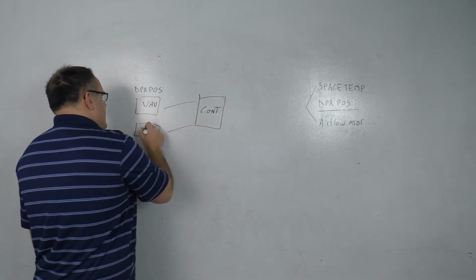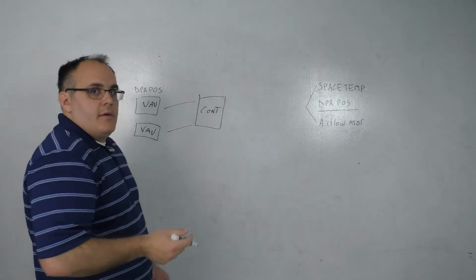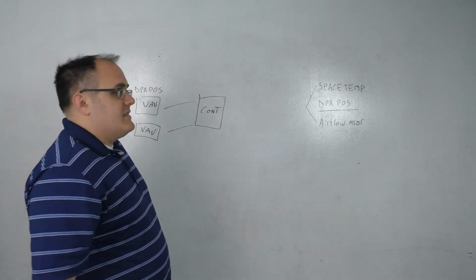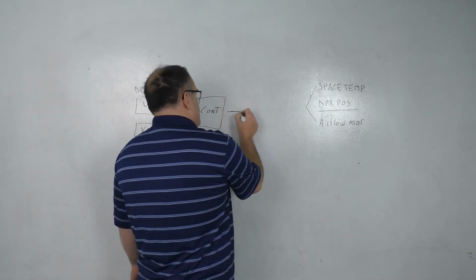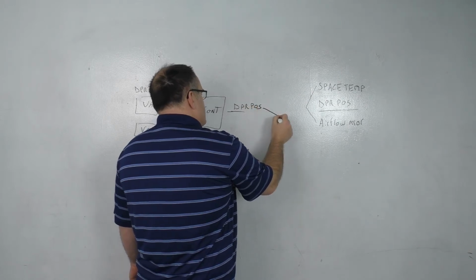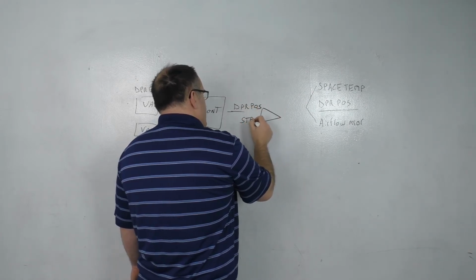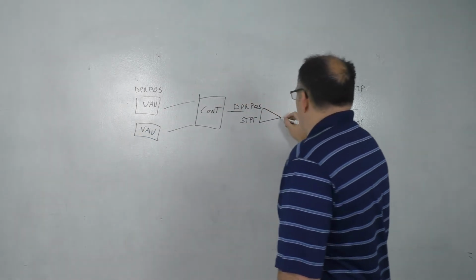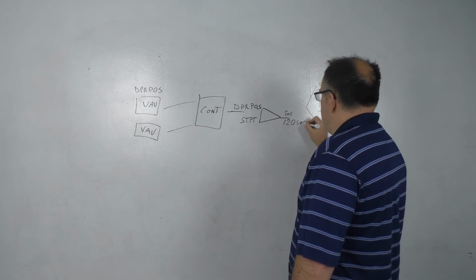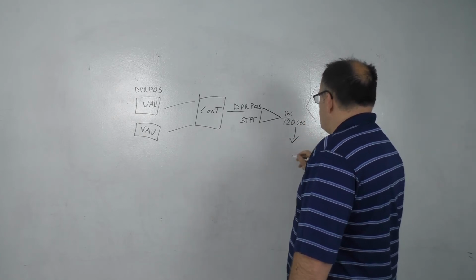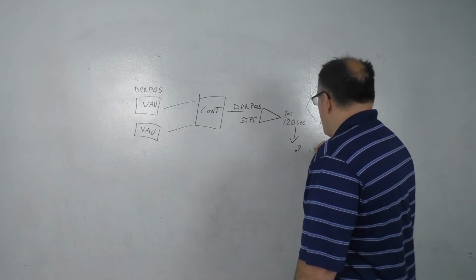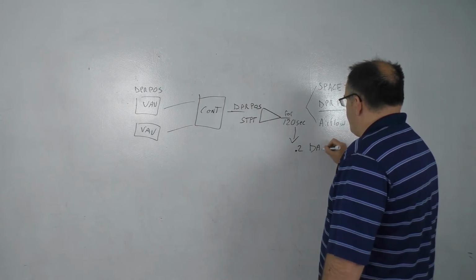that is then averaging or doing a high select of these VAV boxes and saying if DPR, damper position, is greater than set point for maybe 120 seconds, then we increase by maybe 0.2 our discharge air pressure set point.